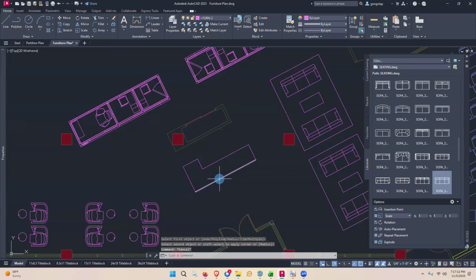And then I have a 36-inch radius right here. So I can use fillets for that. And when I'm in the fillet tool, I can come down here to radius, change my radius to 3 feet or 36 inches, 36. And then I can fillet that.